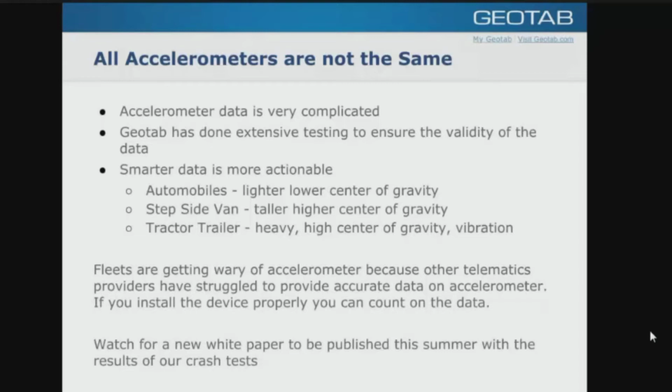Okay? If you look in the engine status data, you will see lots and lots of records of accelerometer data. Lots of things are going on in the vehicle. You think about how much movement you get forward, backwards, side to side, even up and down. Even though we don't count up and down against a driver, we do use it for things like rollover crash detection, and the data needs to be solid. So the device needs to be firmly mounted to the vehicle.